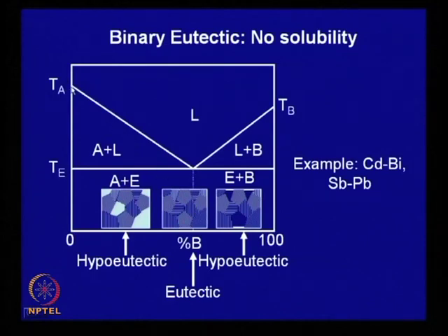It is also possible to plot the liquidus lines, and we will look at one such example of calculating this type of phase diagram. In fact, we have seen one such example in the case of the isomorphous system, where both liquid and solid are assumed to obey Raoult's law, that means both are assumed to be ideal solutions.